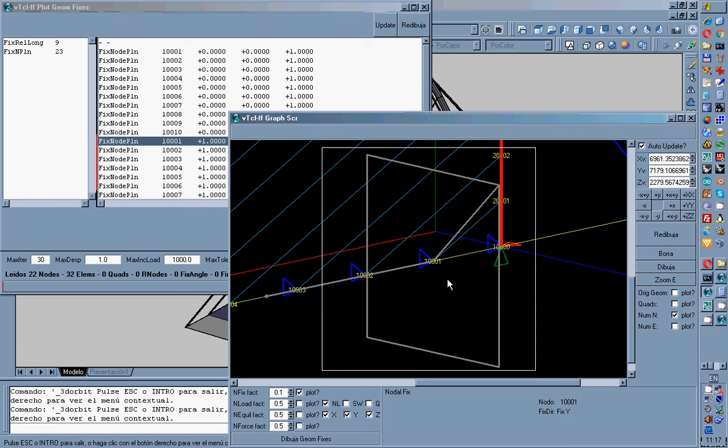So at the end it is going to be a beam here between this side of the bridge and the other side of the bridge. So you can simulate that as a fixation that creates a reaction. But this plane fixation is not allowing the node to move, but it's not creating a reaction. So all the tension in this cable vertically is going to be compensated with the weight of the deck, and horizontally is going to go through compression in this beam.